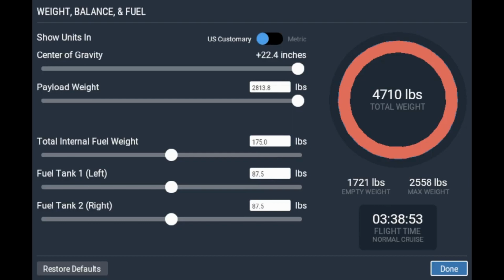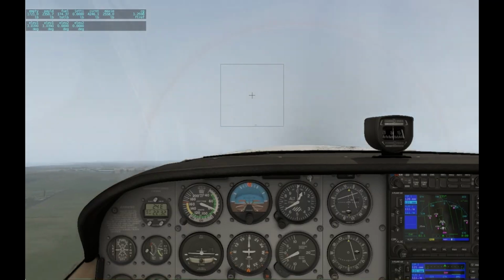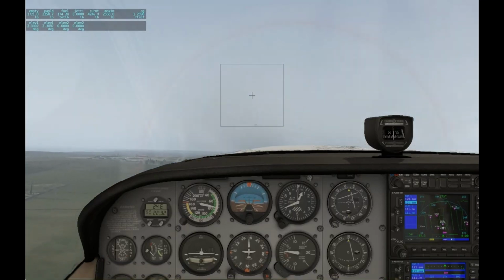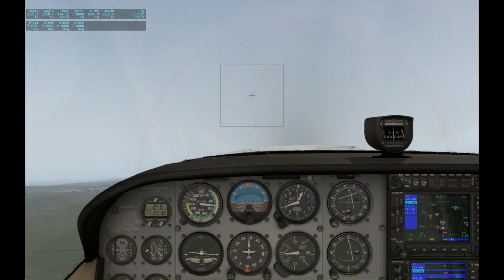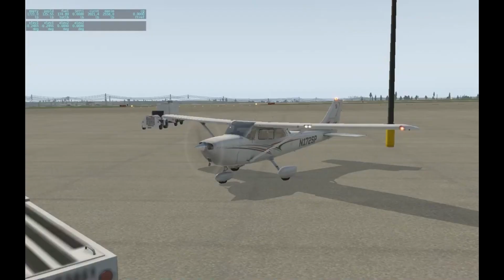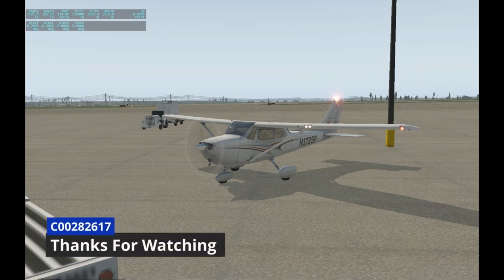We now place the centre of gravity fully forward on the aircraft and also place the payload weight at maximum. Here again we can see this aircraft is quite unstable and it's quite hard to fly. We also have to keep the nose in an upright position in order to maintain level and steady flight. Then finally, the purpose of lesson 6 was to demonstrate how the aircraft's centre of gravity and the payload weight placed at different points on the aircraft can affect the flight stability and overall performance of the flight of the aircraft.